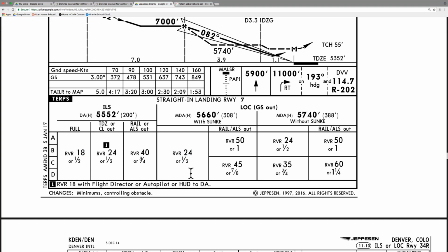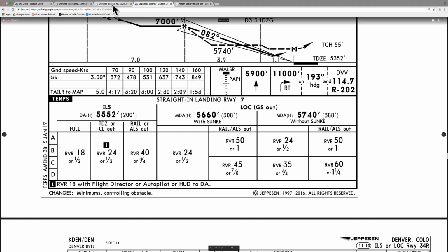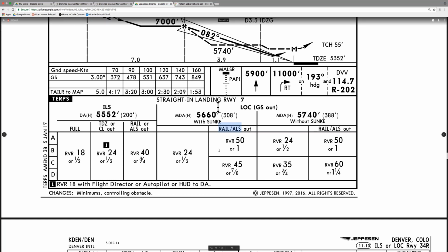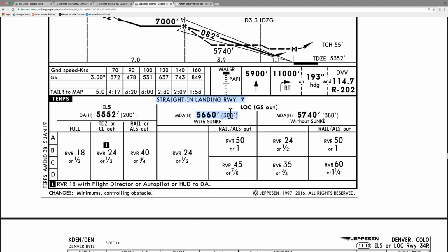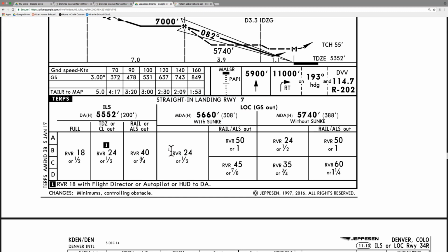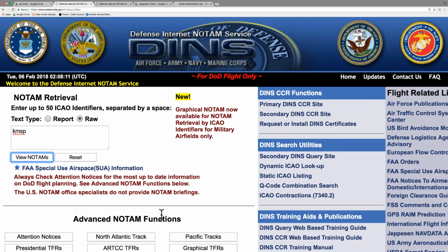So is this pertaining to the 1 nav aid, 2 nav aid rule? Yeah, this would have direct correlation to the 1 nav aid, 2 nav aid rule. But remember, we only applied the 1 nav aid, 2 nav aid rule to what airport? Alternates. Perfect. Exactly. So if this is our destination airport, and this is the runway we're using, it directly affects our minimums.